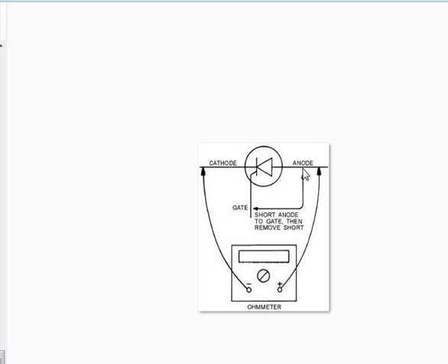First, you put your anode, the red one, this side, and cathode, the black one, this side, and temporarily short the gate and the anode. Some little current will flow from the positive, because they will be shorted. Some little current will flow from here to here. In the process, this will continue to show conduction even if you remove the gate.